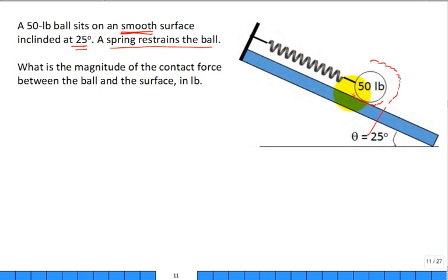So then we come up here, and are we going to have to cut through that spring? Yeah. Yep. What about, hell, let's include the spring. No, you cut through the restraint then. No, you can't do that. That's not going to help. So when I isolate it, I come down to a particle. Don't forget W. What's that? The weight of the ball. And then don't forget the contact. Now, this is a little tricky. The contact is perpendicular to the slope of the plate. All right?